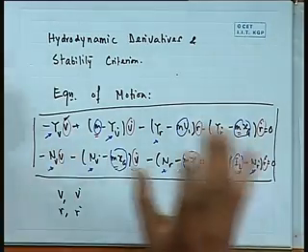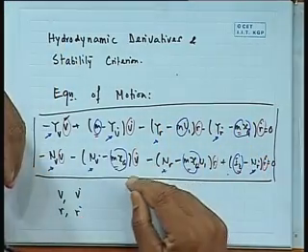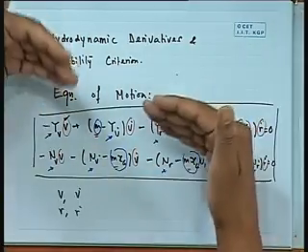But then it sometimes becomes difficult to write them in dimensional form. So, what people do is write them in a non-dimensional form, so that everything is divided by some factor. The ease of it is that the numbers are of the same order regardless of the ship size, and for a geometrically scaled ship they will be the same numbers. It is exactly the same as giving you the resistance coefficient instead of the resistance R and C.